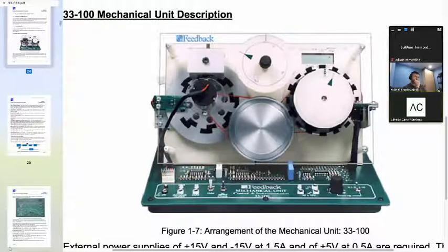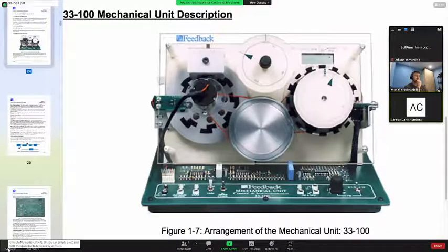The magnitude of this voltage tells you exactly how far away you are from the zero reference. So if the voltage coming out of the 360 potentiometer is 0 volts, that means you are right on the money on the zero line. I don't remember how far this goes, but I think it goes up to 1.5 or something like that in terms of the magnitude.